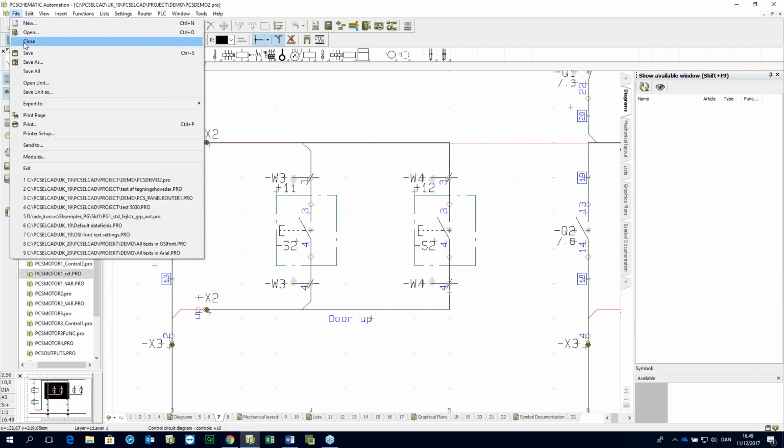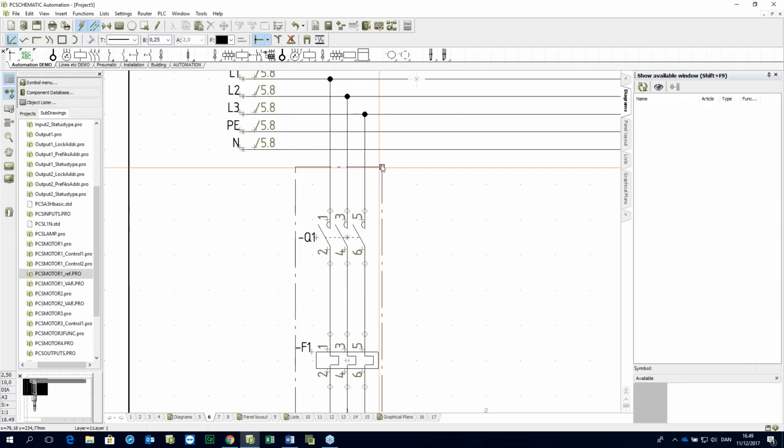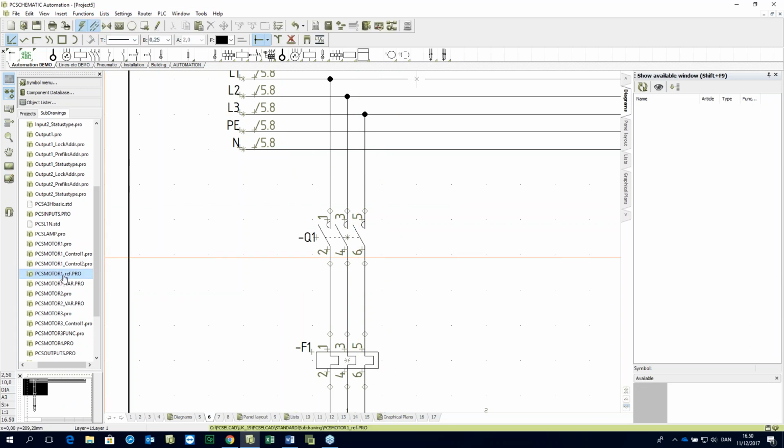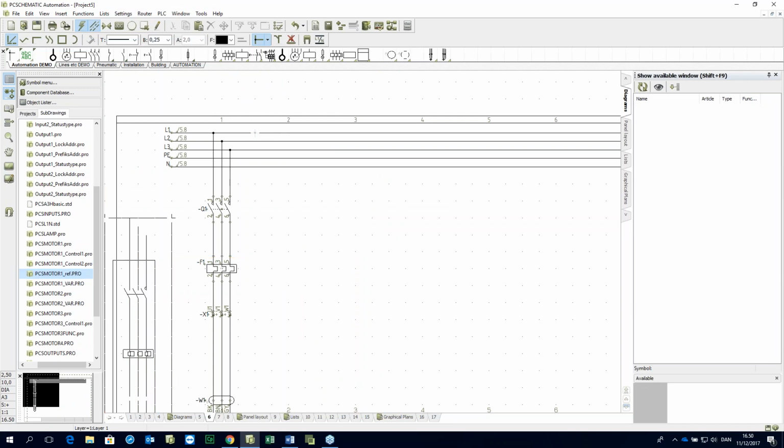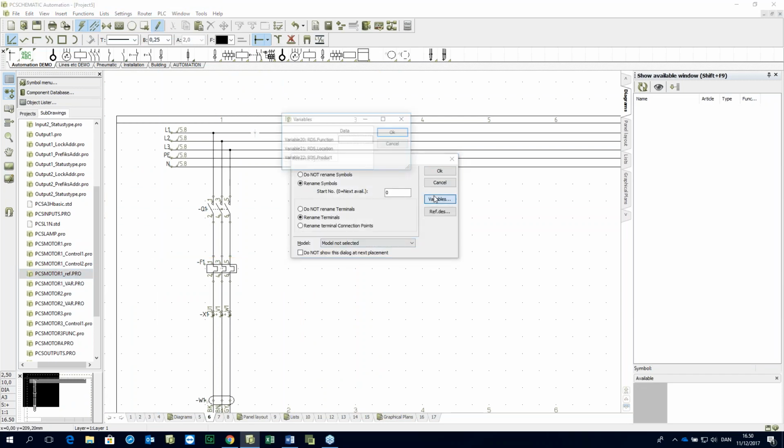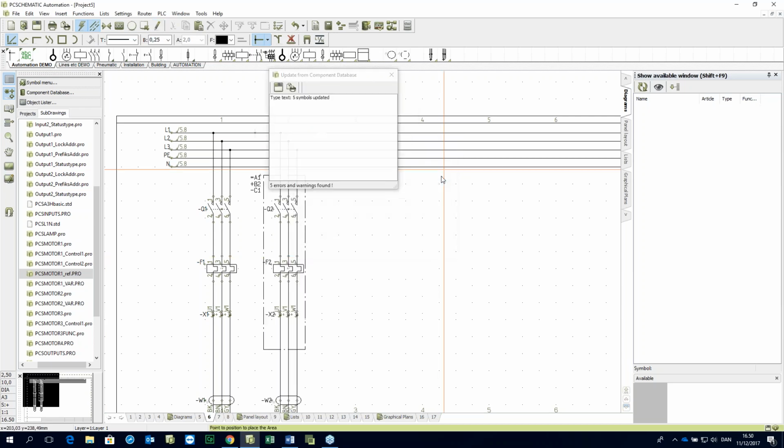And then I'll just close this one here, because now in this one it's empty, so nothing is in it. But if I take this one in again and drag it into my project, then you can see I have variables here. I have a variable on my function. My function has a prefix of equal sign. So if my function is A1, and my location, I'll just call it, is plus B2, and my product is called minus C1, I could type them in here and click OK.